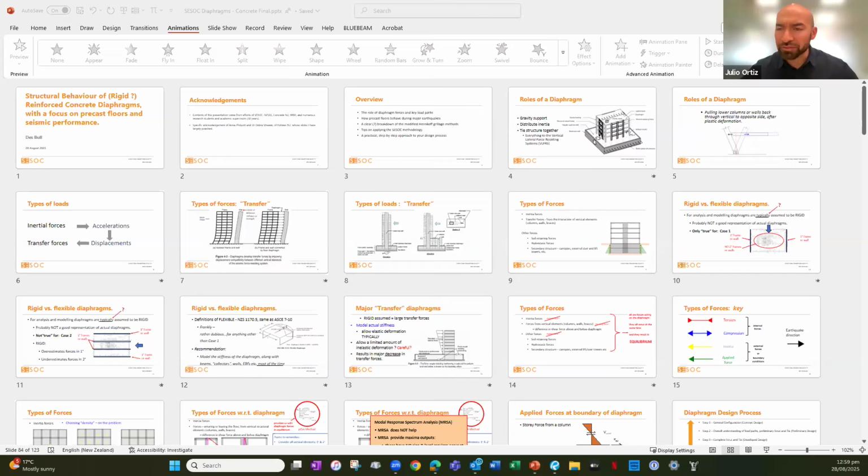Yeah, here, Timothy Blackburn expands a little bit on that. So ACI 318 has some guidance on this. The 2019 version suggests a 0.25 cracked section modifier. We'll be keen for the presenter's thoughts on this.